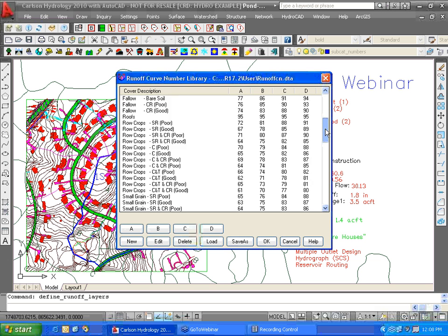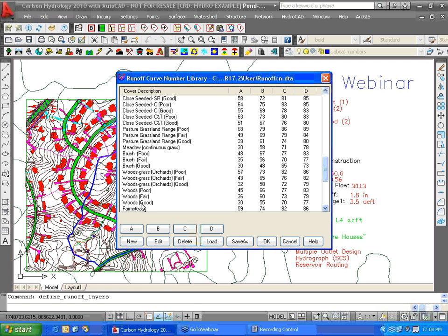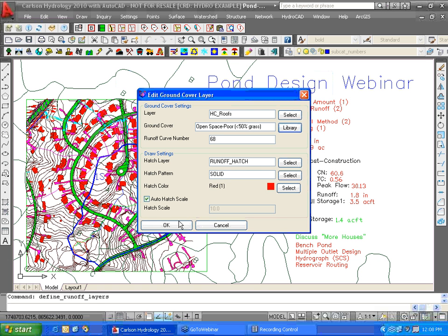So when you have woods, for example, good woods would absorb more of the rain, let less runoff, lower runoff coefficients or C factors, curve numbers. We have quite variable results depending on the soil type.